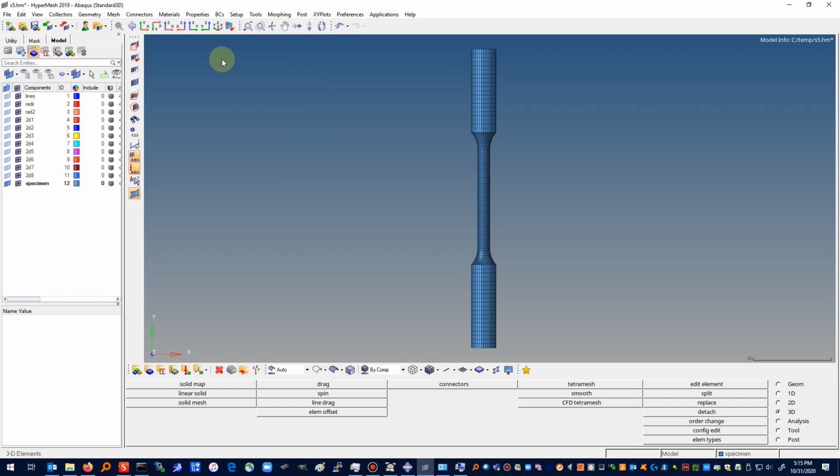Alright, now inside of the specimen we need to check some things. We're going to turn off all the elements from the 2D geometry. Only leave the 3D elements showing. Yeah, there's what it looks like in a line view. We need to equivalence this. As this spins around, it creates two nodes on that final surface.